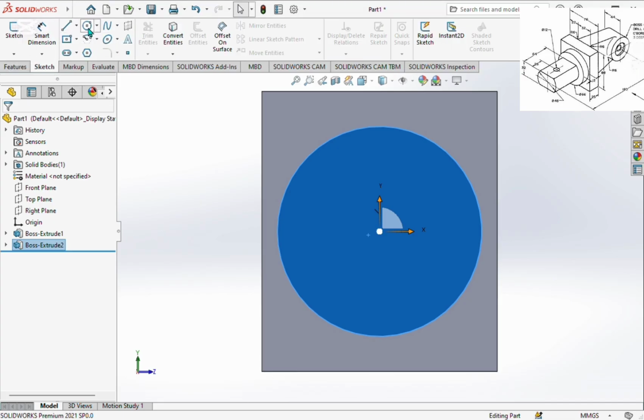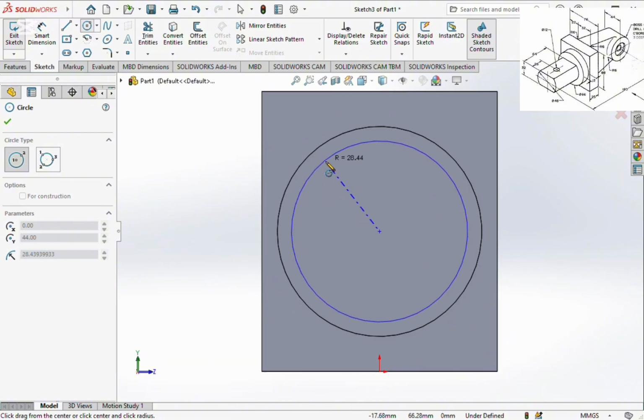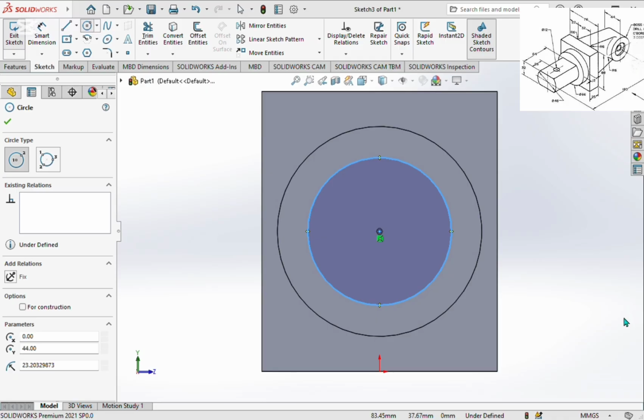Now when I have this, I'm going to use my circle command again. Now I already have the midpoints, which is from here. So here you can see it will highlight on its own. You have to make sure it's the exact one. So you can see it highlights based on the former circle I've done. So when I click it, I will just drag it to get a smaller circle. But now the diameter is 48, so the radius will be 24. So I will take 24, then I enter.